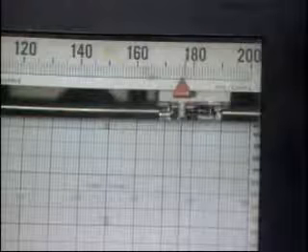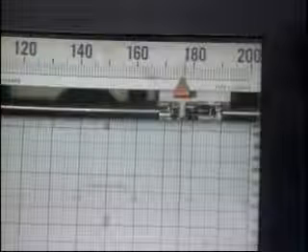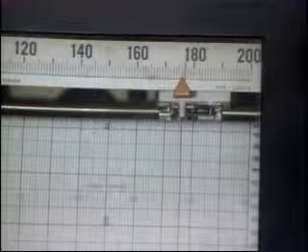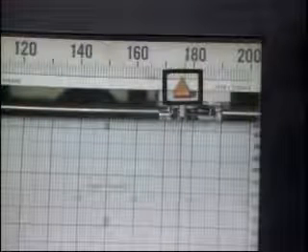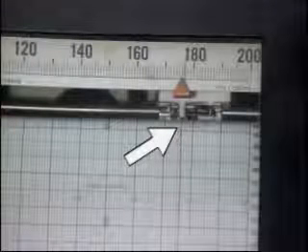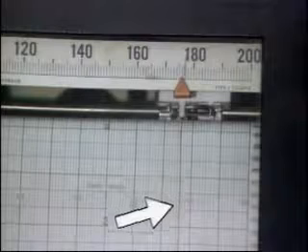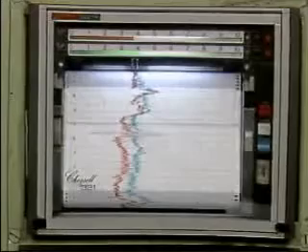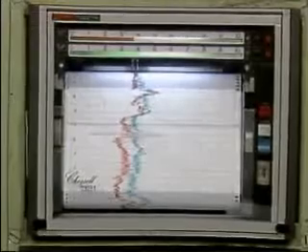This particular instrument is called a strip chart recorder. It has a paper chart that moves slowly through the recorder during operation. A pointer at the top of the recorder indicates the present value of the variable being monitored, while a pen marks on the paper chart, creating a graph that shows the value of the variable over a period of time. Some recorders can record the values of several variables at the same time, or the same variable measured at several locations in the plant. They're known as multi-point recorders.